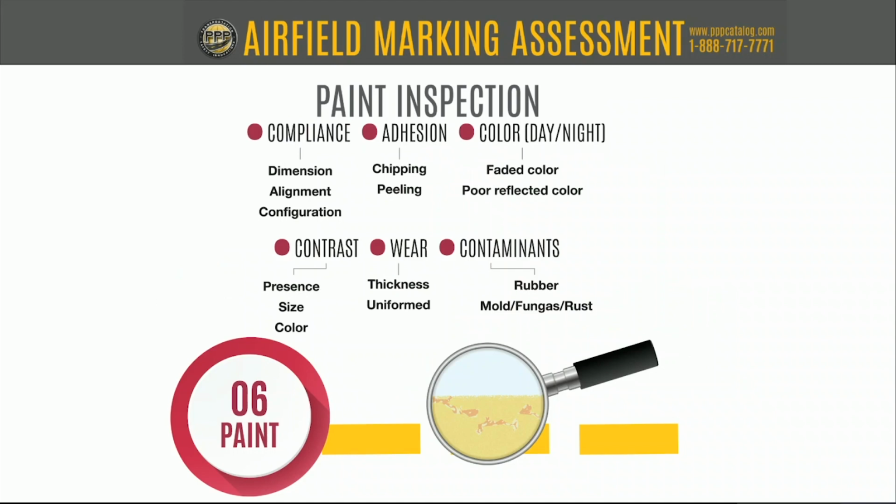I'm going to go out on a limb and say that everybody listening to this webinar has had some degree of chipping or peeling, because I see it constantly. The other thing that we see a lot is the color and really the quality of it, whether it's faded. And faded, I think, is an overused term in our industry. Faded, by definition, really means that the UV and the sun have started to deteriorate the pigments and the color of the marking itself. So many times, not only in airports, but inspectors and everyone say, oh, the markings are faded, it's time to repaint. Not necessarily true, but the sun does have an impact, particularly on reds and pinks.